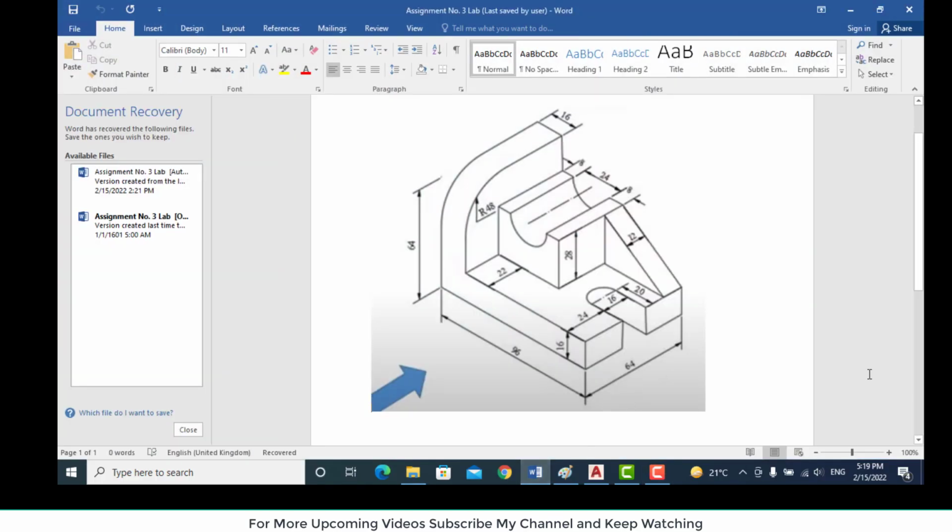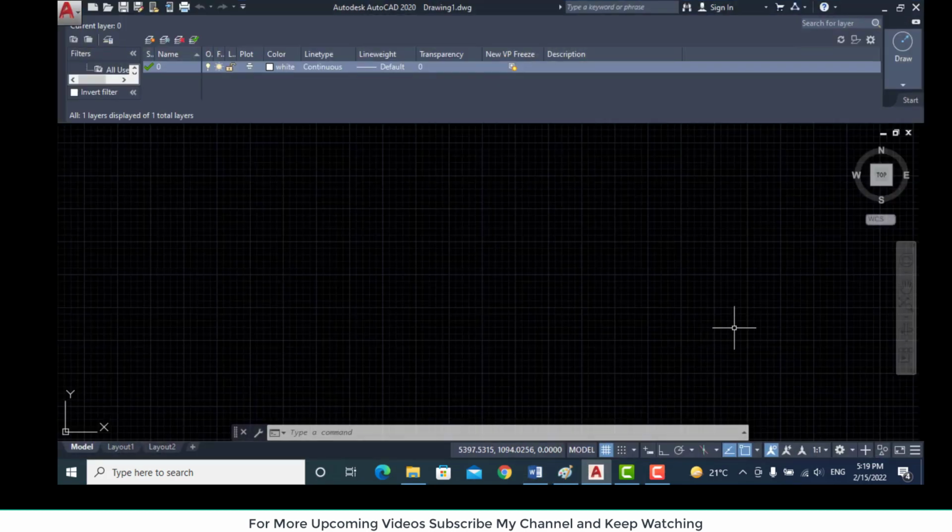Bismillahirrahmanirrahim. In this lecture, I draw the three views: top view, front view, and right side view of the given drawing. So, first, I draw an A4 page in AutoCAD 2020. In landscape, the length of an A4 page is 297 mm and the width is 210 mm.